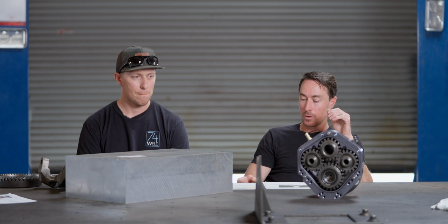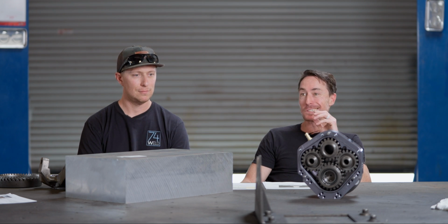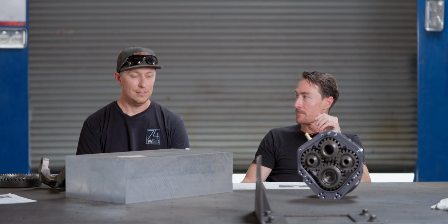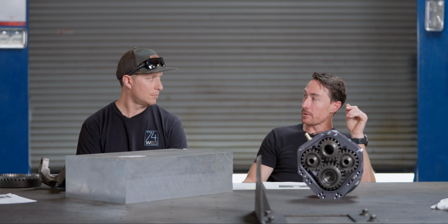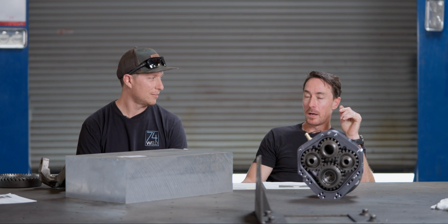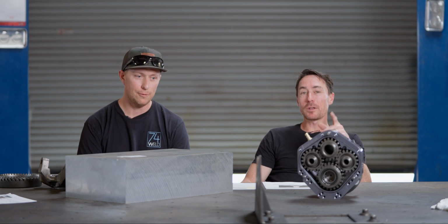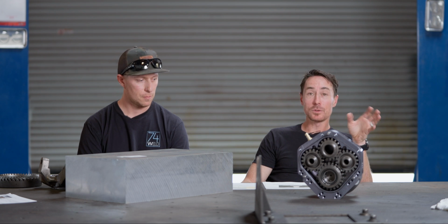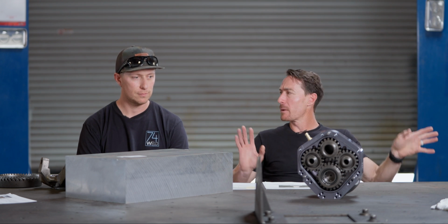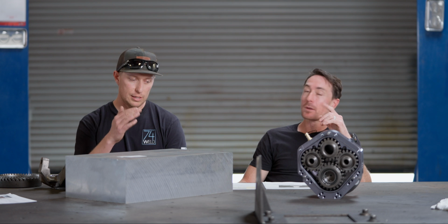Yeah. So, I look at, Ford's not doing it on the Bronco, clearly, because we've seen those uprights snap in half. Yeah, that's cast iron. That's cast iron. But they are doing it on Raptor. Okay, I haven't seen that one yet. And they are also, Toyota, we had the 24. So the 2024 Toyota Tacoma went from a cast upright, the new 23 and older is cast. We're talking about the Gen 2, it's probably forged. Oh, it is forged. Yeah, Gen 3, it's a forged steel. Yeah, because you can weld it. People do the gusset kits all day.